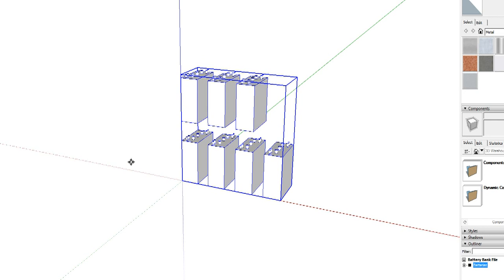Next what we want to do is start with our shells, and the part of the shells we're going to start with is the sheet metal that the battery is going to be on. This is because it's in direct contact and therefore can be directly referenced to the batteries. One other thing we need to know about SketchUp is that we can't put holes in our components after they're made. So we have to compensate for that by putting the holes in the sketch.